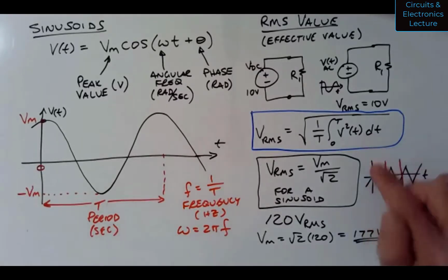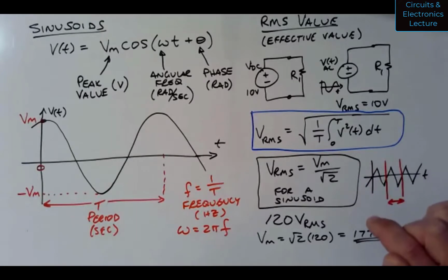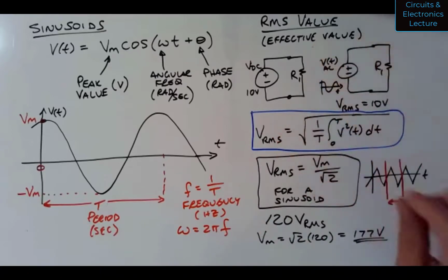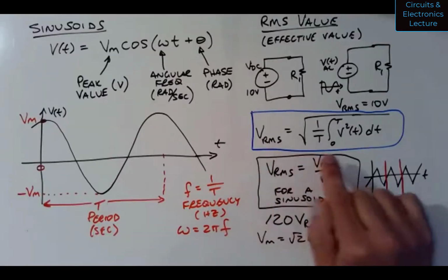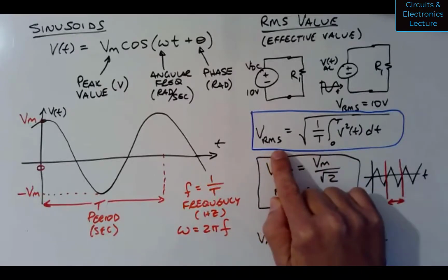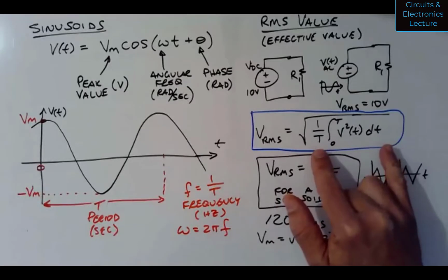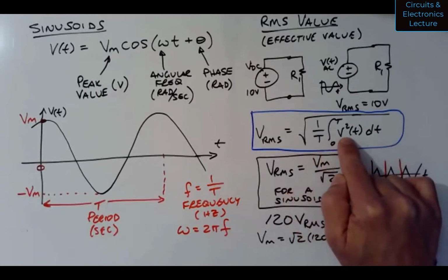But basically, the RMS value, and this is sort of hand wavy, trust me, is the effective value because it describes the voltage that you need to use in V squared over R to calculate the power. Okay. Right, so you have to use the RMS to calculate power in V squared over R, and RMS is described by the root of the mean, that's the integral with the 1 over T, of the square of your voltage.